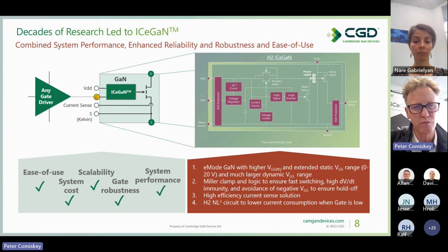Ultimately, we address a number of issues with traditional E-mode GaN: low turn-on threshold, sensitivity to voltage transients, low VGS range, and also a need for GaN-specific drivers.